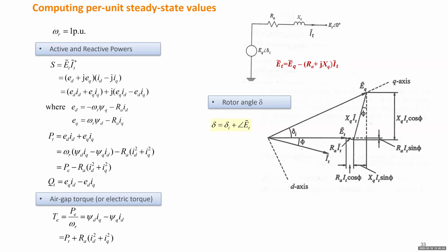We draw this vector by turning the direction of current counterclockwise by 90 degrees. So the total will be the voltage drop on this entire branch. Then that will be the Q axis. Later, we assume the Q axis to be the imaginary axis, and the D axis, which is lagging Q by 90 degrees, will be the real axis, if we use complex numbers.